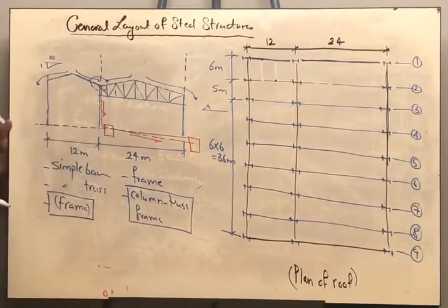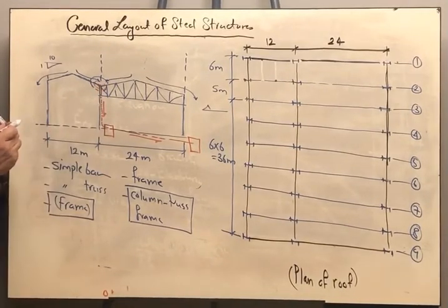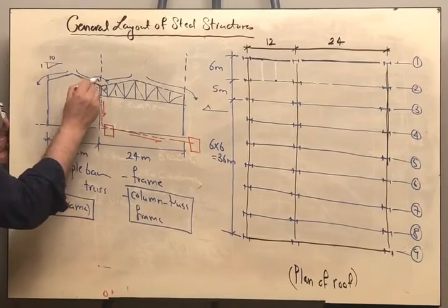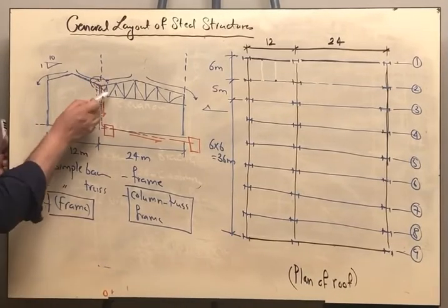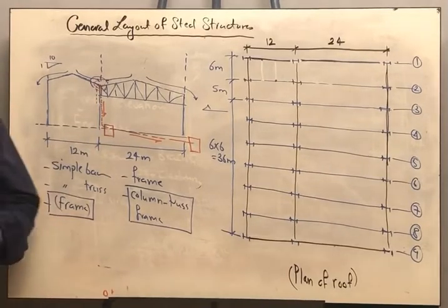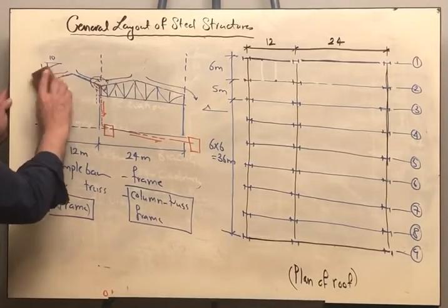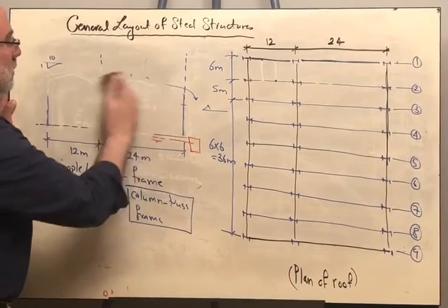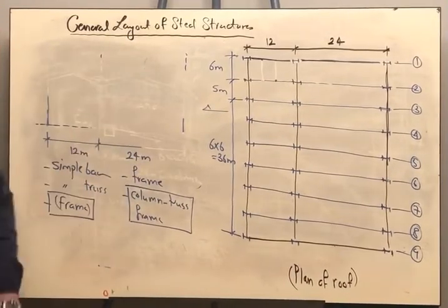Always this system is not preferable because it is possible that this drainage will be closed somehow due to dust, due to the leaves of the trees or something like that, and water will collect here and will start leaking inside the structure. So we prefer not to have such a thing inside our structure. What will be the option? We can think of something else.